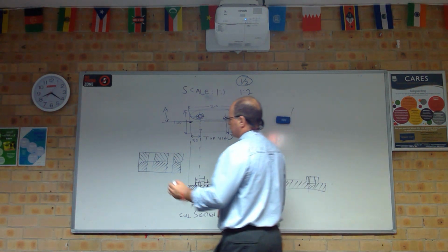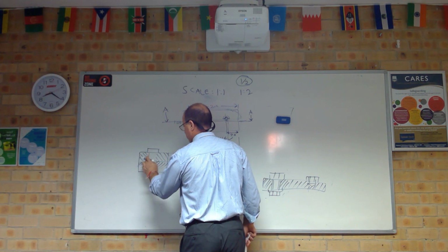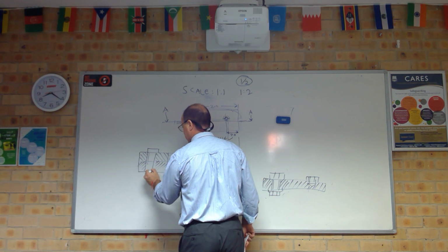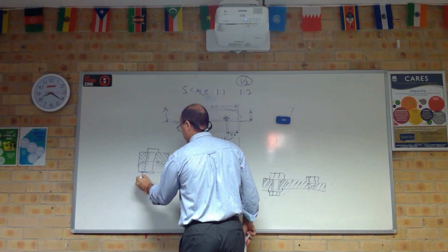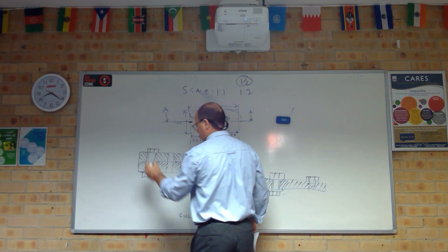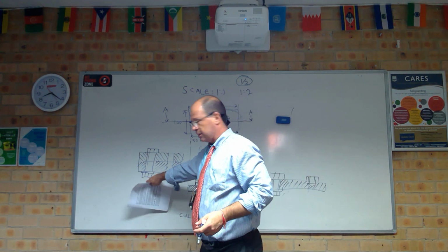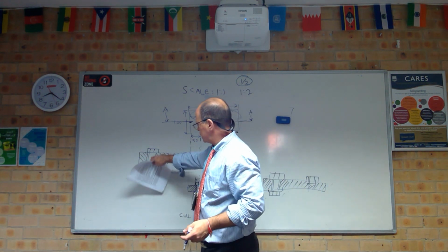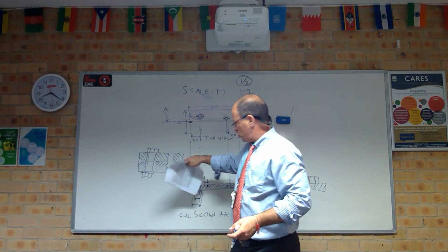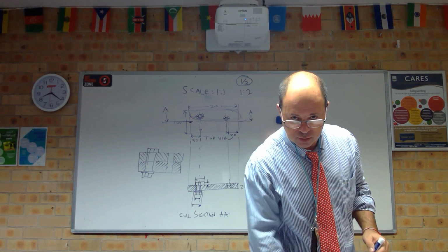And then you're also going to be putting bolts in here, so you're not going to go across the thread lines. Okay, you go to a washer and a nut. So this will be practice at drawing heads of bolts. It'll be practice at drawing our nuts. It'll be practice at joining two materials, okay? And it'll be practice at following instructions as well.